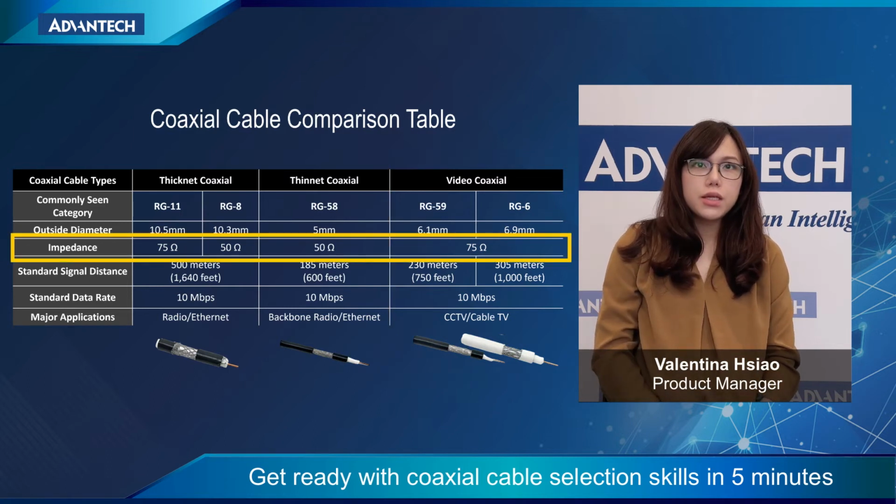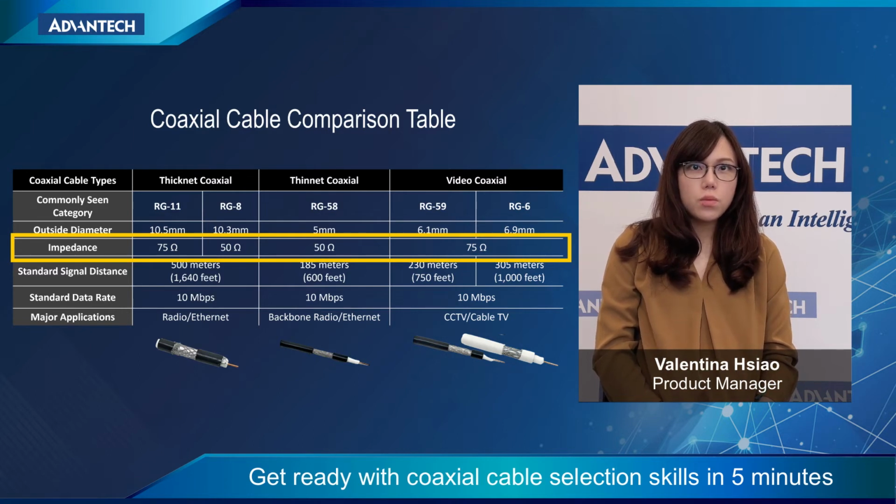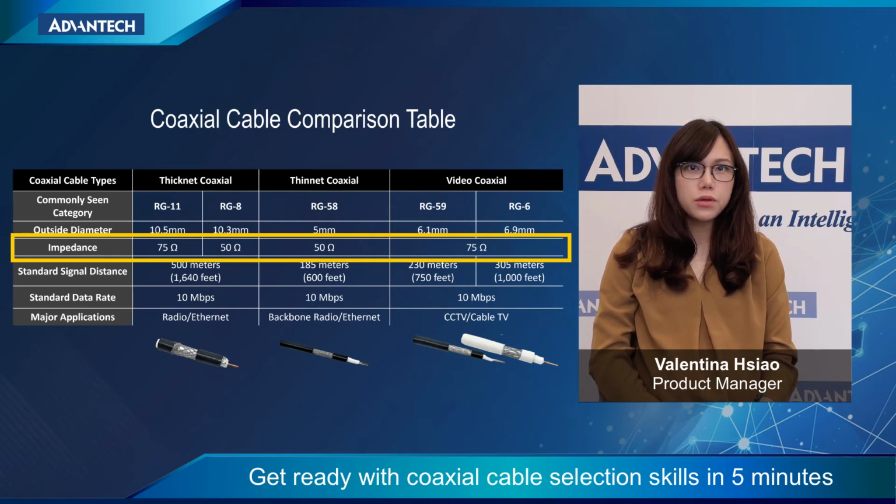There are two main types of coaxial cables in terms of impedance: ones with an impedance of 75 ohm and ones with an impedance of 50 ohm. Cables with 75 ohms are mostly used for video signals, while 50 ohm cables tend to be used for data and wireless communications. When users are installing cables, besides its RG rating, the impedance and connector type should also be considered to be paired with the to-be-connected devices.